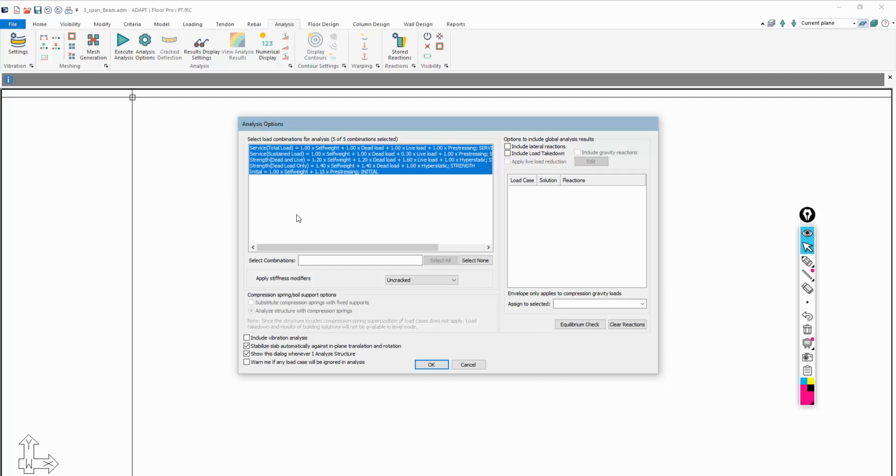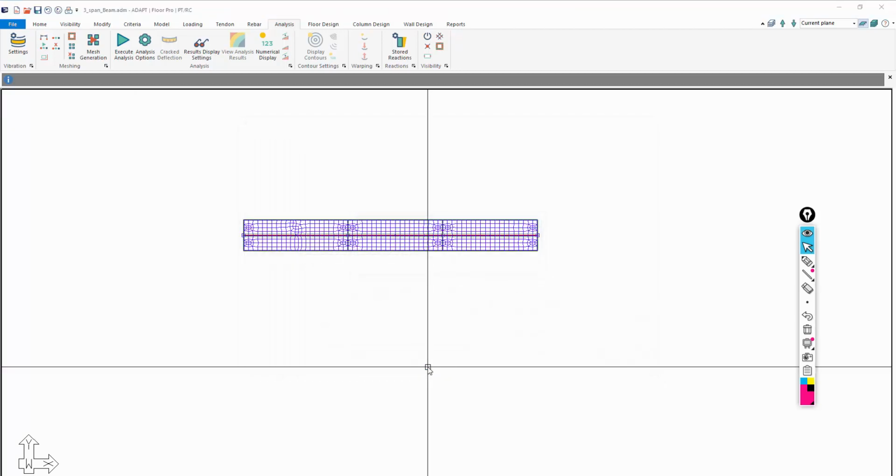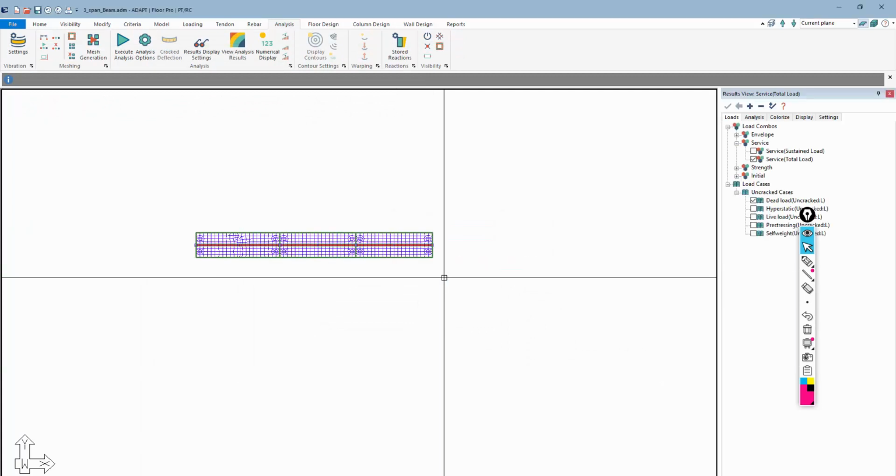Here our targets are really just to determine the requirements for serviceability, pre-compression, allowable stresses, balance loading, and then beyond that, if we're looking at deflections, we can look at that in more detail. So strength, we're not going to really worry about until we have some outcome for the post-tensioning cables necessary to control the serviceability conditions for the beam. So we'll just design and analyze now for those combinations.